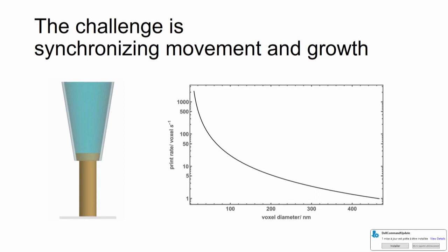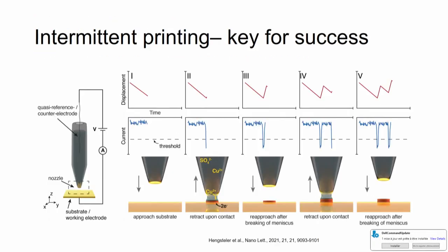And what we found out, again, is that you can still synchronize the movement of the nozzle at a micrometer scale, because the relative deposition rate, so the rate is here in the vertical axis, at the size of hundreds and thousands of nanometers is relatively low. However, as you reduce the size of the nozzle, you will see that even the tiniest variations in the nozzle dimensions would lead to drastic changes in the print rate, so you will never manage to synchronize your printing based on the experiment with one nozzle and apply it to another one.